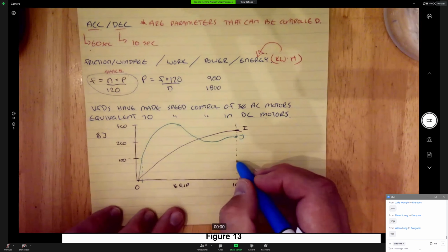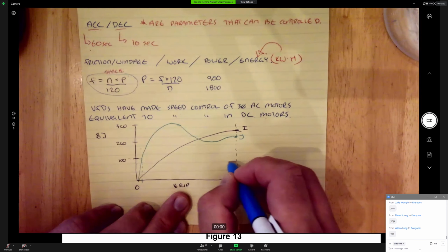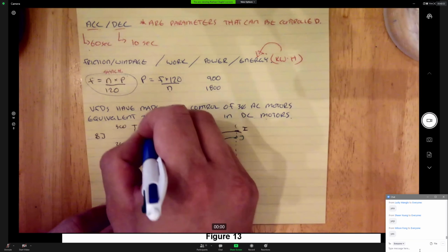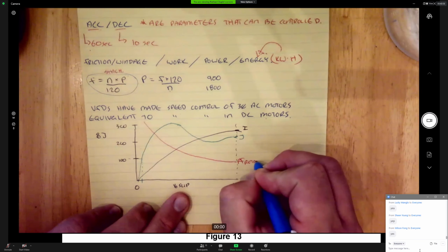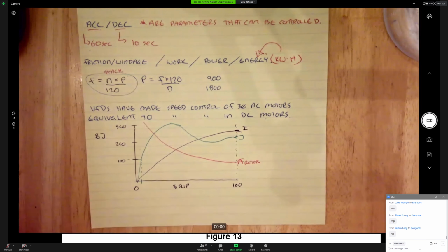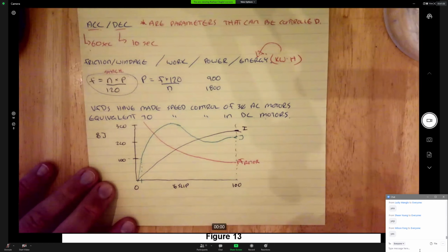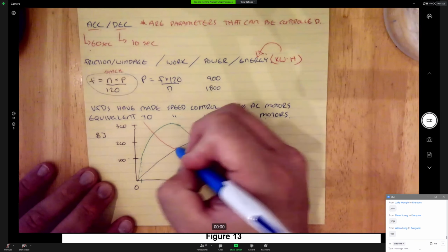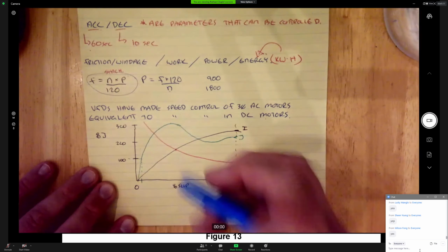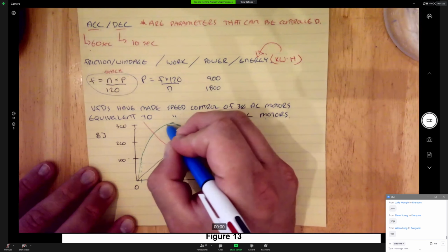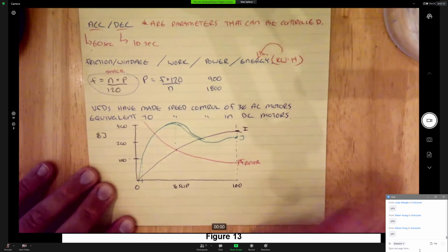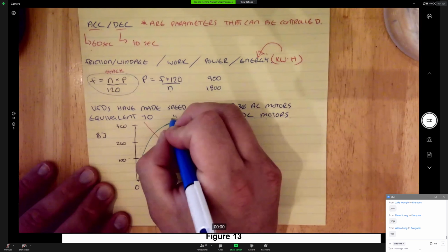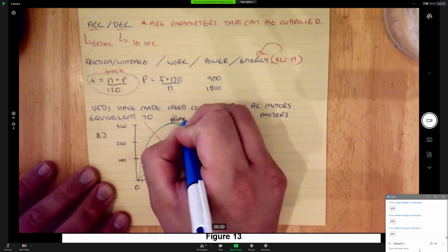And there's one other thing that's changing here. And that is the power factor of the rotor. So I'm not talking power factor of the motor completely. I am talking the power factor of the rotor. And I want you to notice that right at this line here, and we've drawn it mostly as it should be, right at this line here is where breakdown torque occurs.